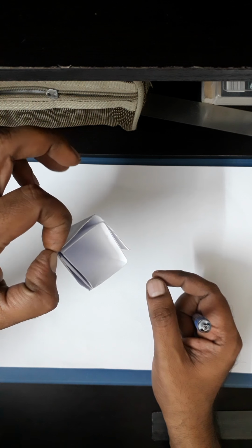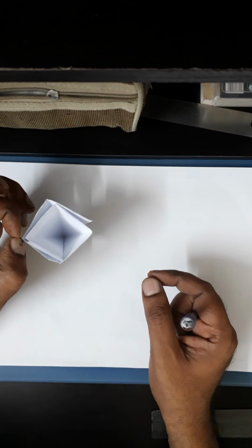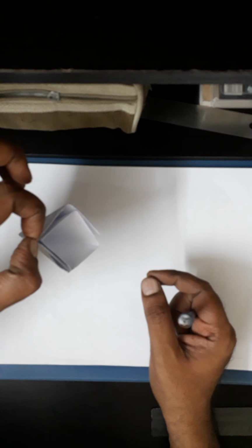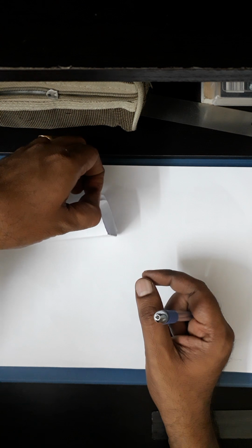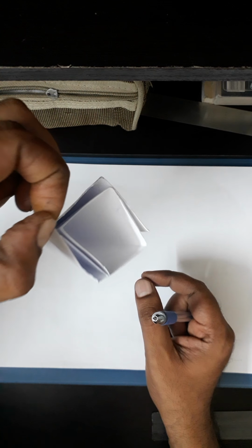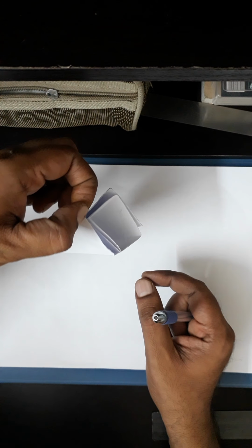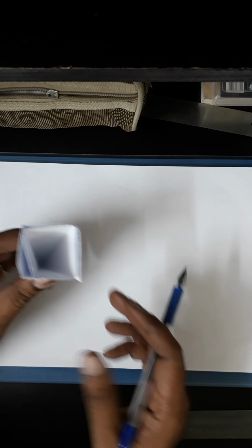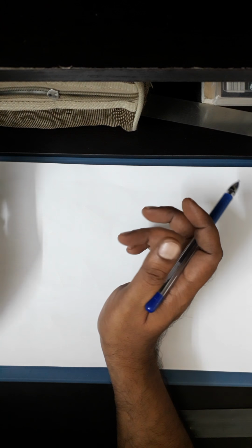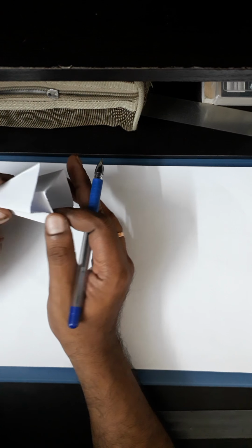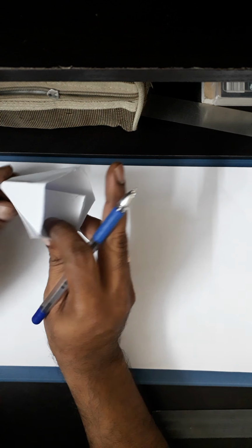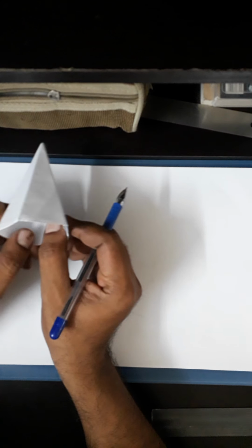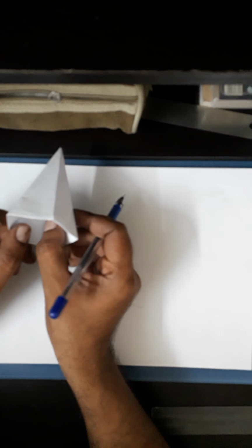So for that, it is better to keep the pyramid resting on the apex, then just lift it about the corner, freely suspended about HP, so it will incline in this position. So I will go for the procedure. Any pyramid, this will be the procedure. Always they are going to give you a pyramid. I'll go for a pentagonal pyramid of, say, 30 mm base edges and a height of 70 mm.